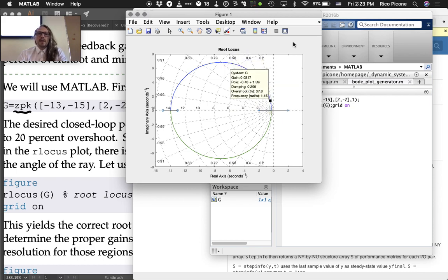We want a 20% overshoot, which you go from 0 here to 29.2% overshoot at that point. So we've got a big jump there. But there's going to be a crossover point at which we had 20% overshoot. But if you keep going, we're going to increase past 20% overshoot, and then we're going to come back to it.